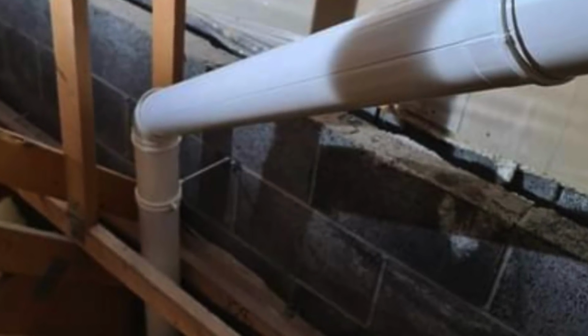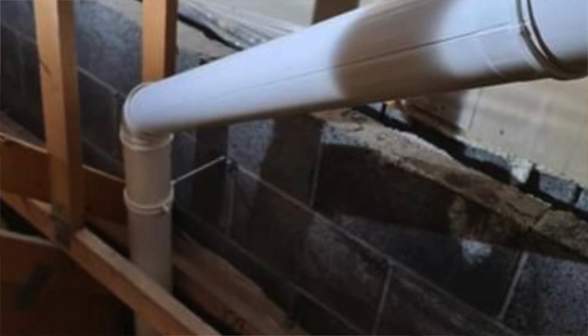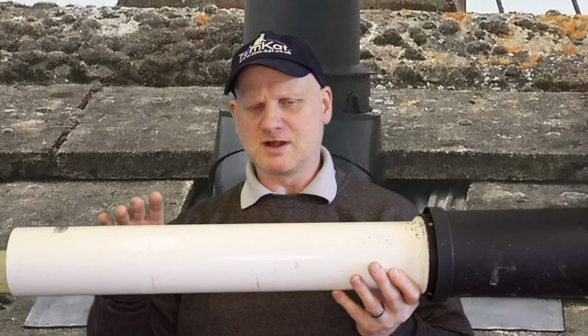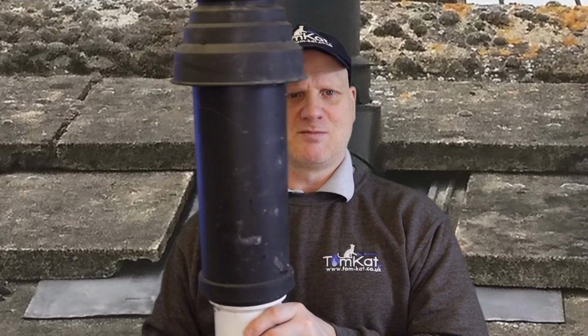A change of direction. Manufacturers say for this type of flue we should be looking at 1 metre, even though the regs say maximum of 1.8 metres apart. So again, follow the guidelines from the manufacturer on where we put the clips, but it needs to be properly secure, otherwise next engineer who comes along is probably going to find it's disconnected.